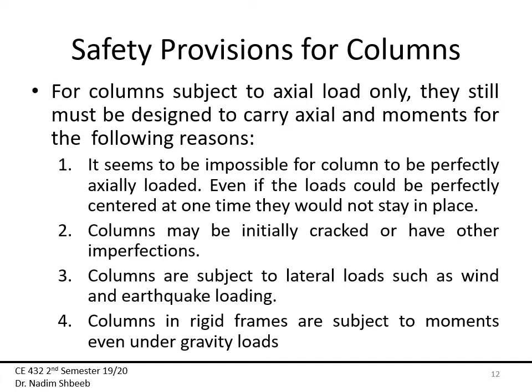Now the other thing is columns subject to axial load only. Well, that's not completely true, although we are assuming that it is purely axially loaded, but we do know that loads shift, and as they shift, you cannot have a perfectly axially loaded column, so we must account for moment, slightly, okay, for it to be able to handle, right?